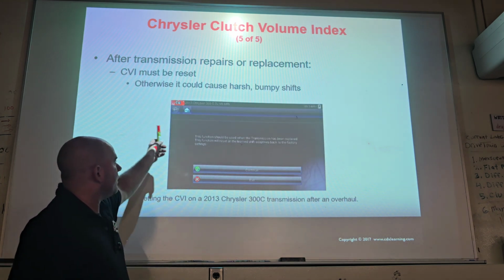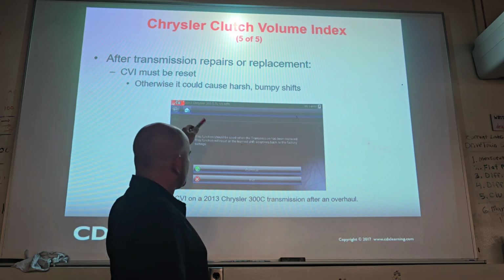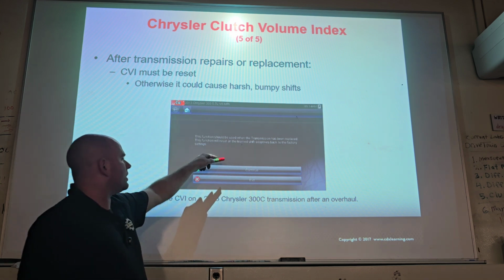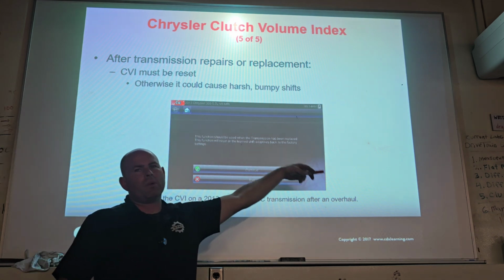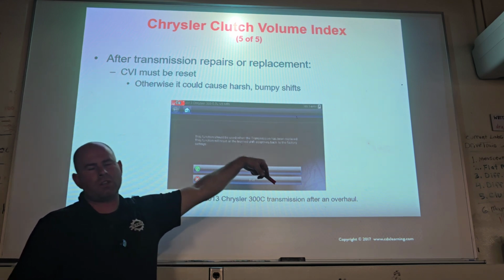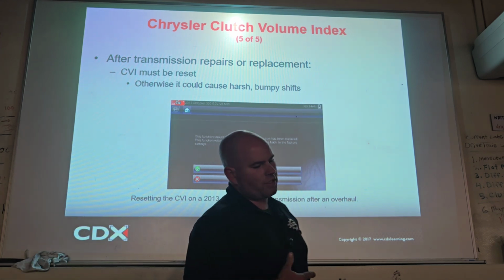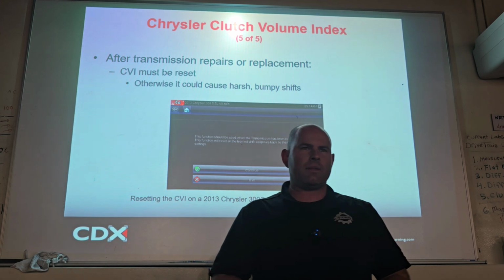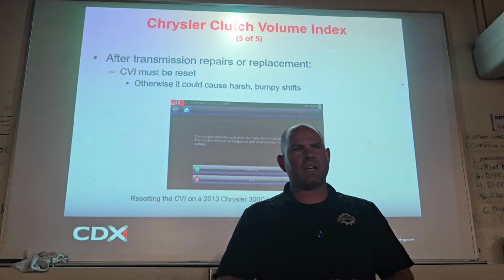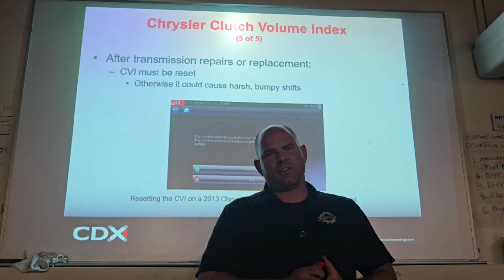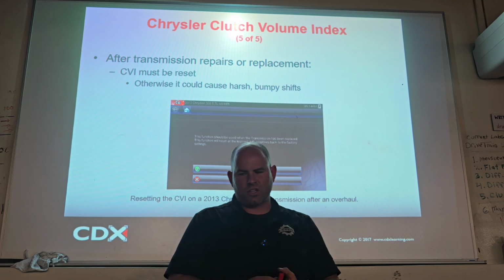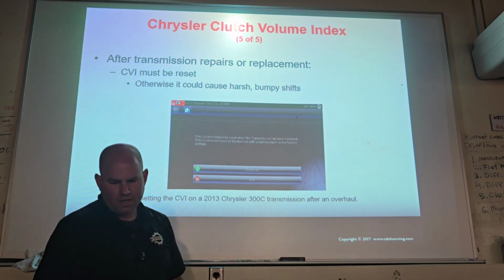And here's the reset. You can go in and say transmission adapt pressure reset. Do you wish to continue? And this is just saying you should really only do this if you replace the transmission. But there have been some times where a transmission comes in shifting weird, and I'm like, all right, as a baseline, let me hit reset. And if it fixes it, cool. And if it doesn't, well, this one didn't really cost anything. So you could do that.